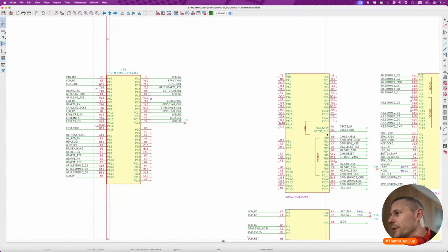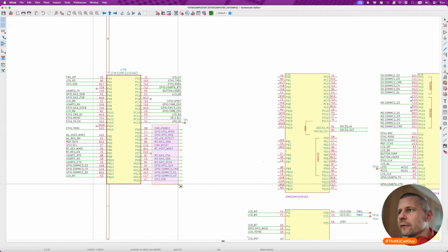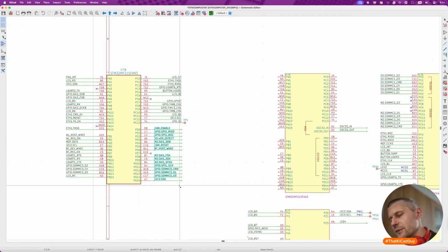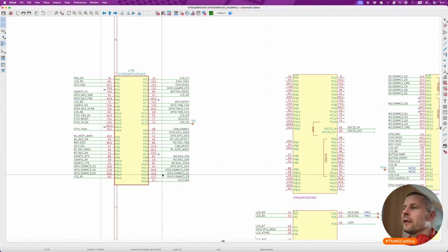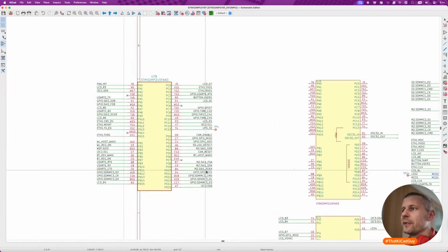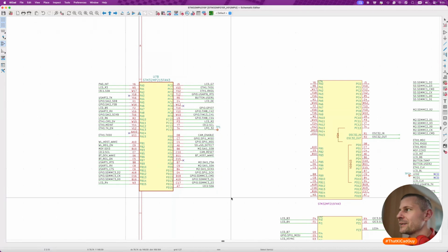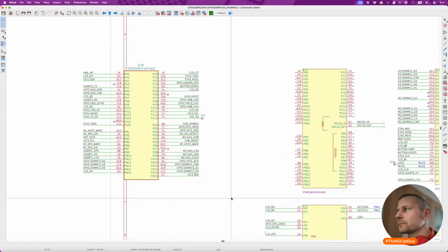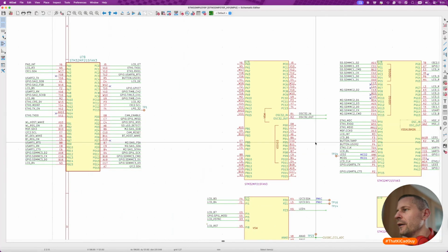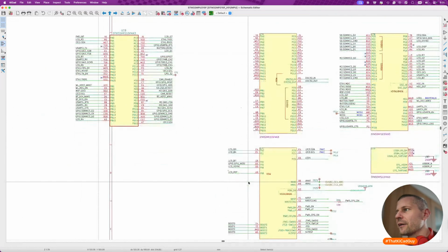Okay, PD 16 nets as well. This, and again mark or select the labels, mirror them and move them to the end of the net. If you don't mind the ends of the nets marking that there is something missing, you can keep it. Okay, these two symbols are unassigned, nets are unassigned, will be done later.